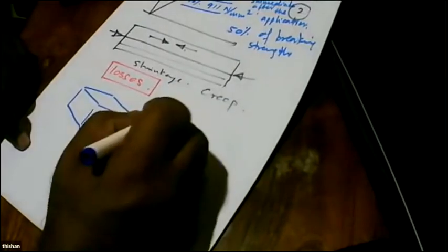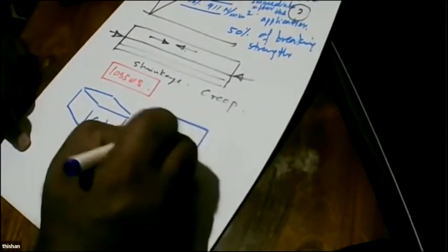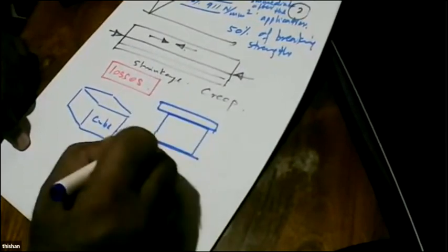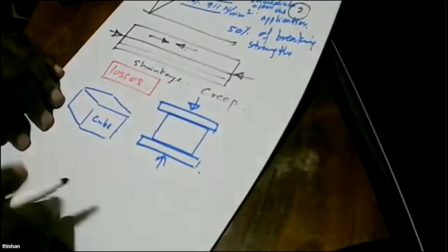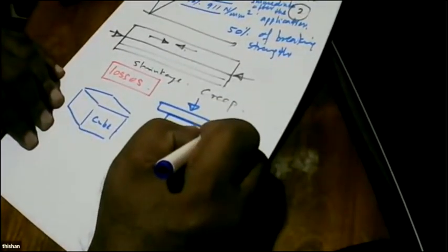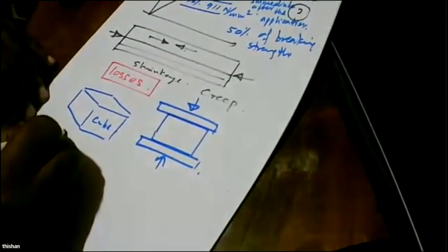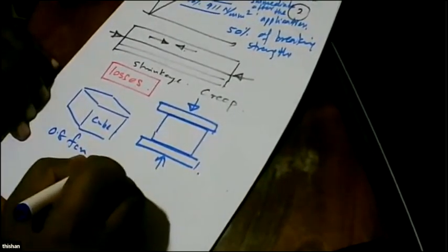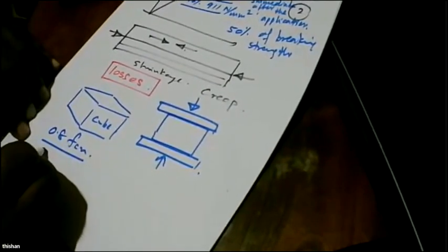And so we know when we apply the stressors in a cube, we apply the stressors, and so you get the actual strength as 0.8 times FCU, and then when it's subject to flexure, we divide it by 1.5.